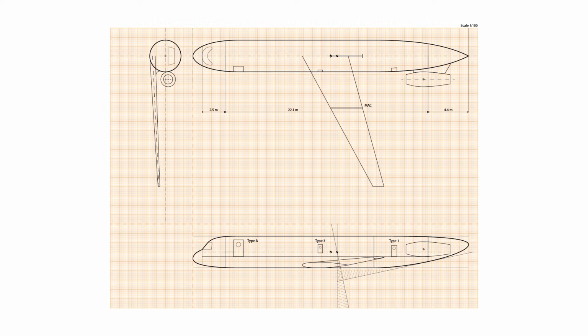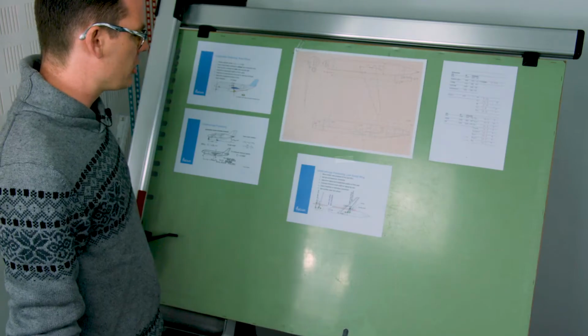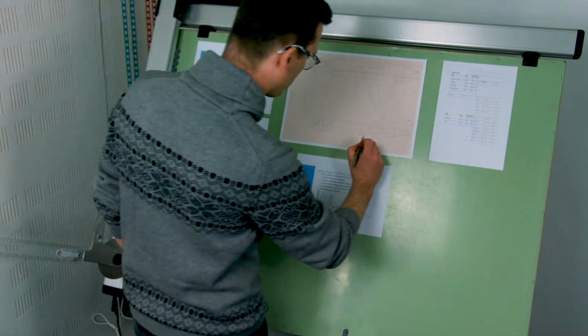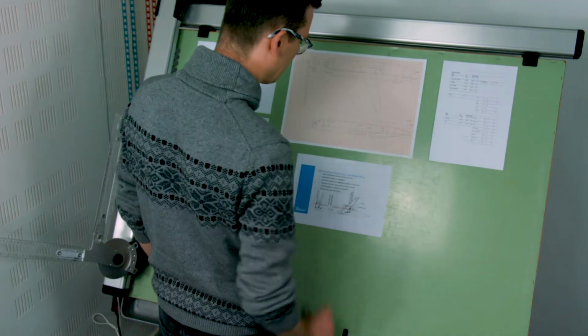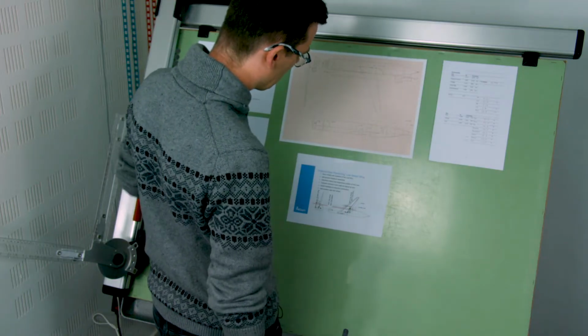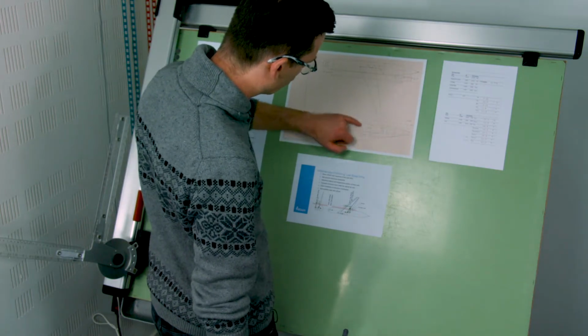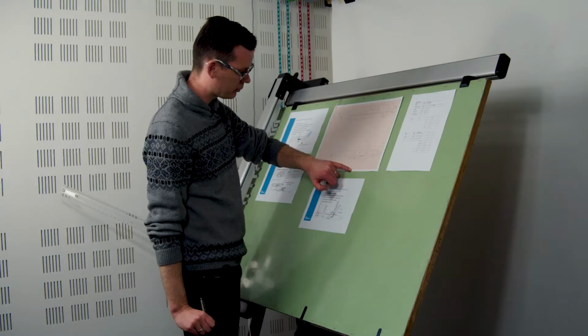That's 1, 2, 3, 4. That gives me my axle position exactly at this point. It's about 4 millimeters below that scrape angle line, but still behind that longitudinal tip over constraint.